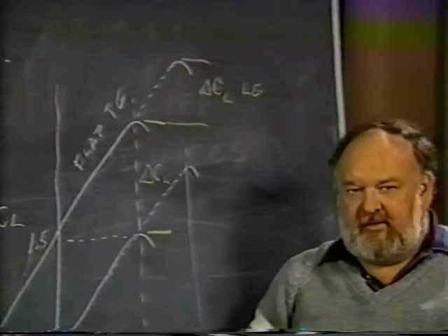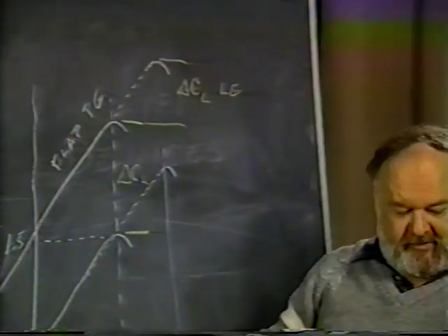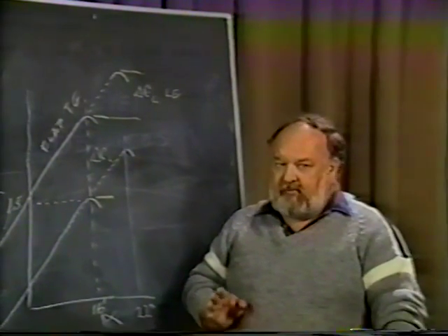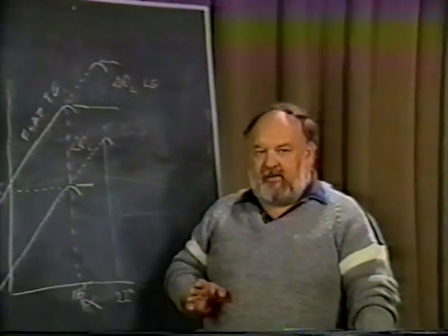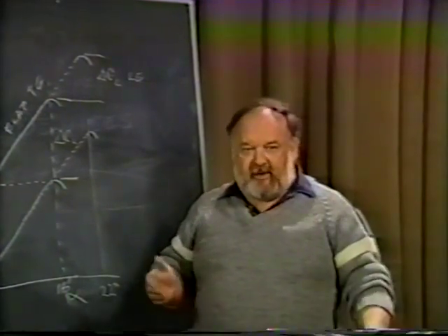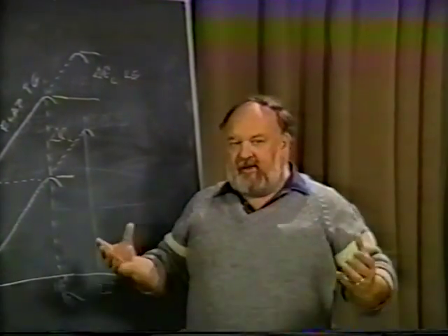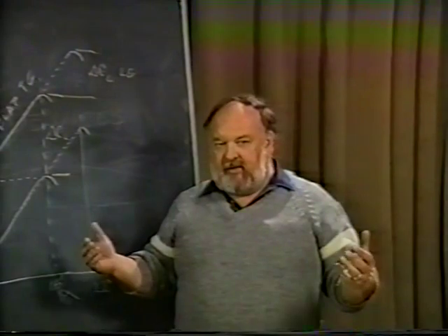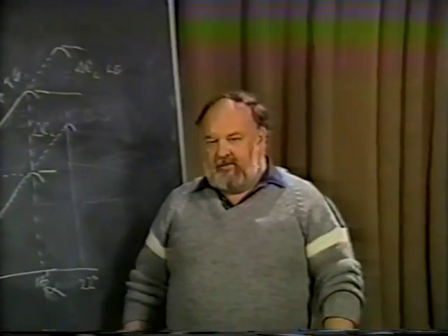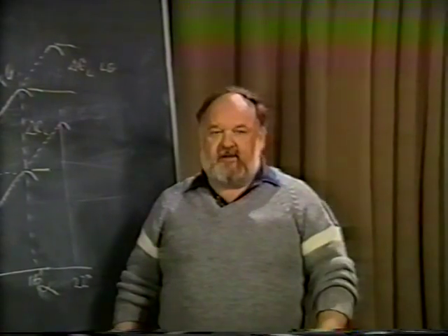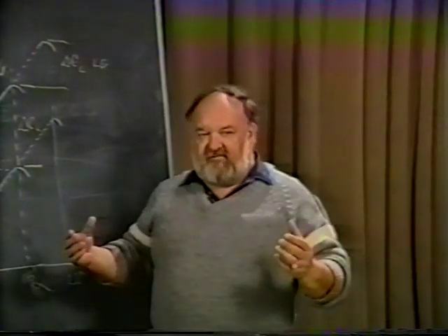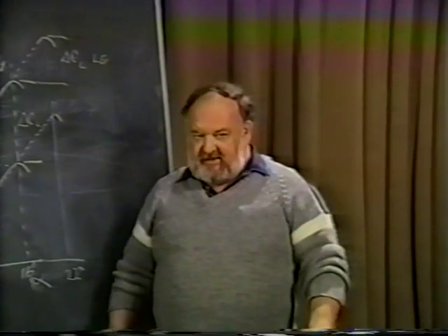Trailing edge flaps and leading edge flaps are very, very powerful devices and very useful, and really should be used on practically all aircraft designs. There are some places where obviously you don't want to use them. A sailplane ends up with a lot of wing area, a high aspect ratio wing. It doesn't really land at a low speed. It doesn't need to land at a low speed. It has a relatively low wing loading already. Therefore, a trailing edge flap for high lift devices is not practical.